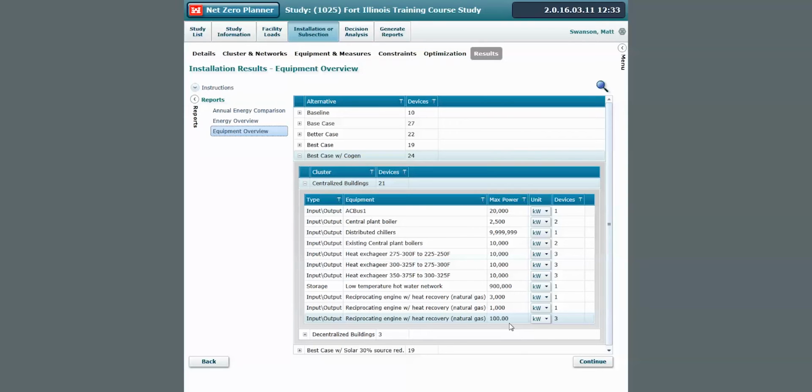This is the first level of planning level study. You could always go back and either, A, work with somebody else to further develop this, or B, just look at some common sense changes to the sizing. You might select a couple of 1 megawatt units, or two megawatt units, so you're back up to that 4 megawatt capacity. Something like that might make the most sense as a final design size. But this very quickly gets you very close to the ballpark of where you want to be looking in terms of the scale of generation and how that fits with your cluster. So let's see what impact that had on the final numbers.